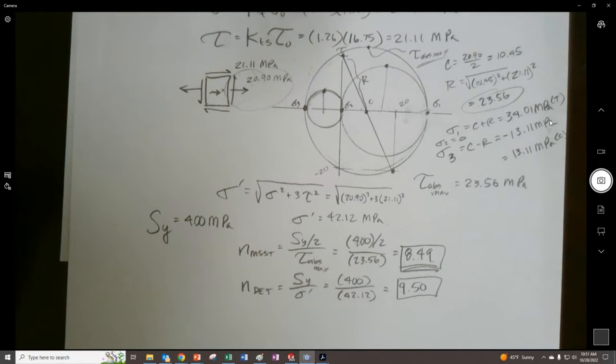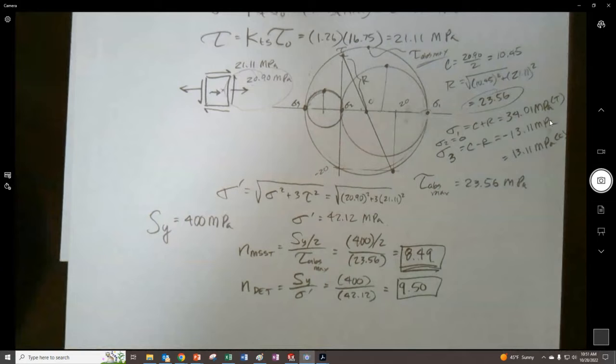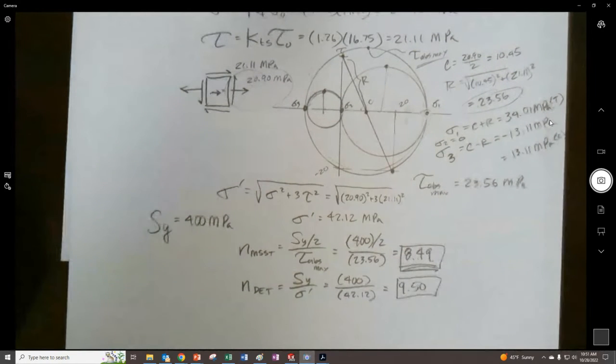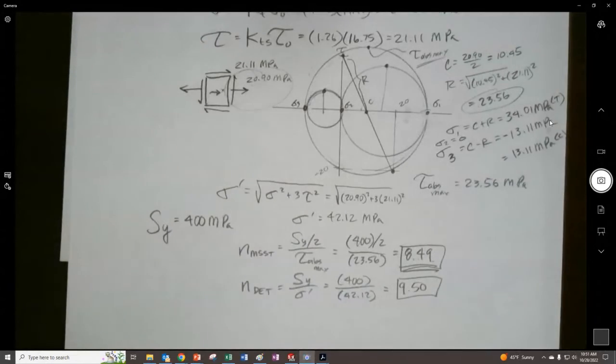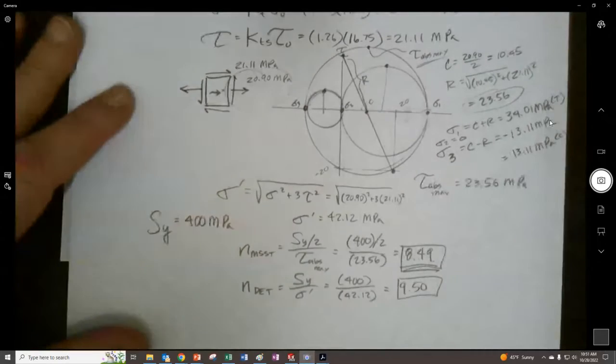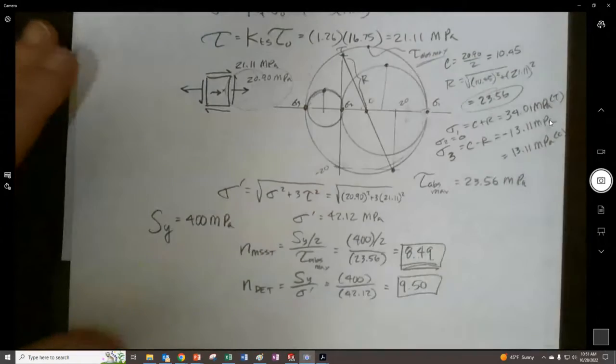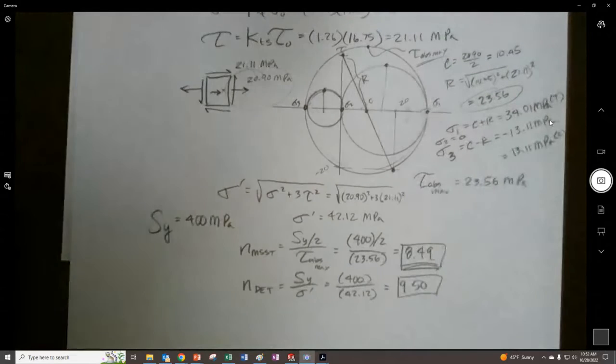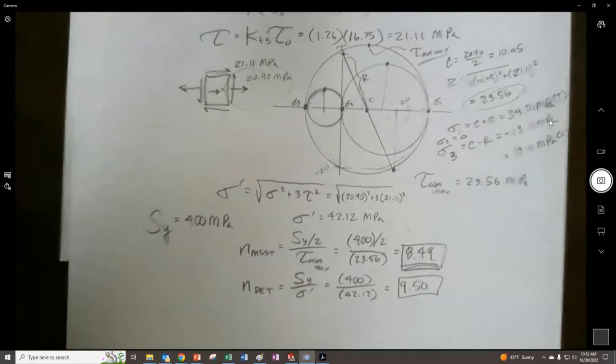I actually had one question about this problem. We did the moment maximum of this because we're trying to find when the stress is max. Yeah, it's usually the case where we want to figure out where it's going to break, right? A lot of times, the safety factor might be for a specific spot, like maybe in a question. But the truth is, we just want to see what's the worst thing that could happen here.